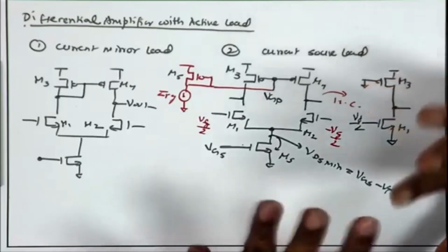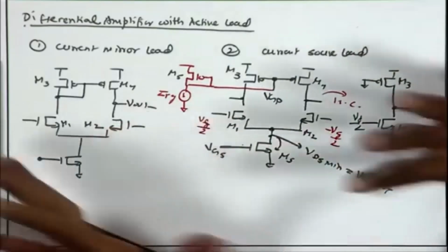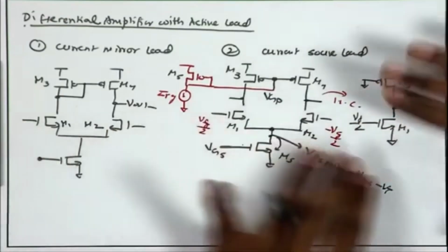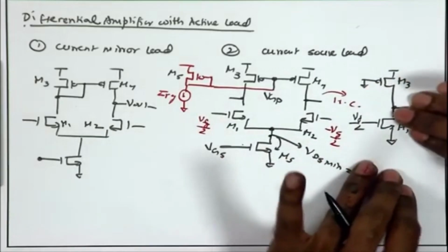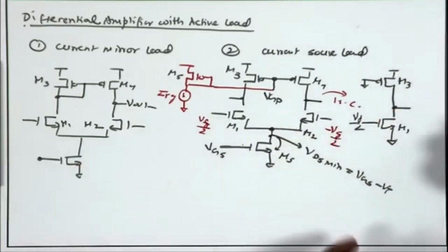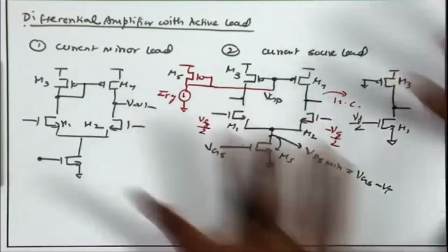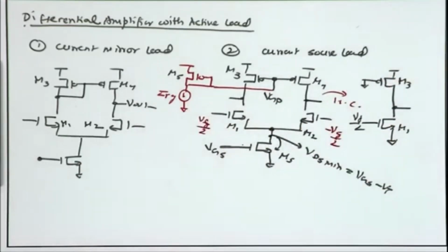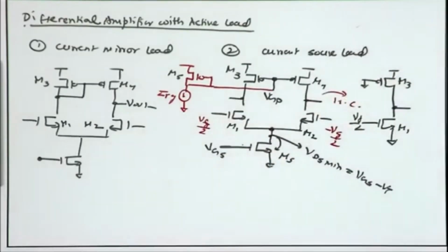and apart from that, the rest of the analysis for the differential circuit remains the same as what we have done. The considerations regarding the bandwidth, the noise and the small signal gain all remain the same. So, we do not have to discuss much about these four analyses. However, we have to discuss something about the biasing. How do we bias the DC nodes, the drain nodes?